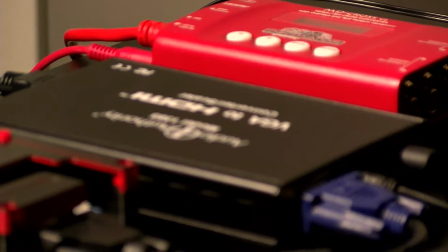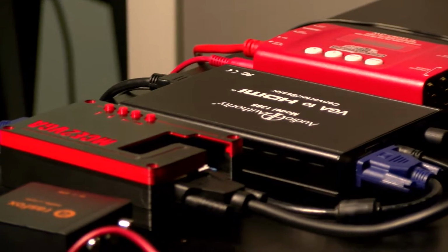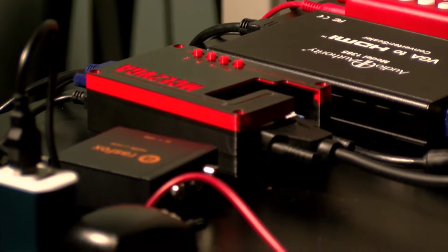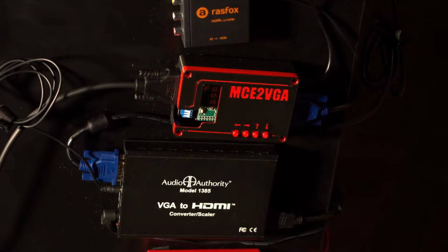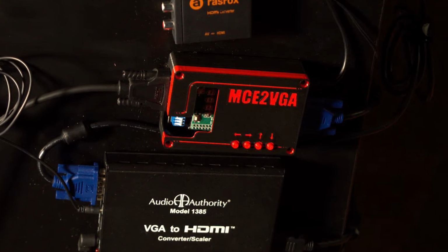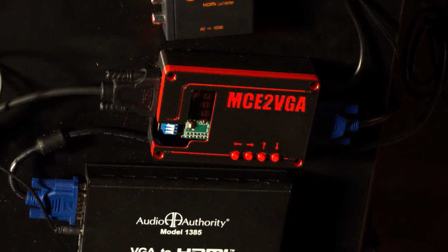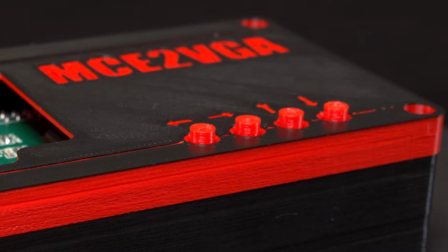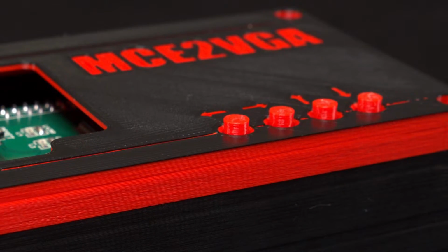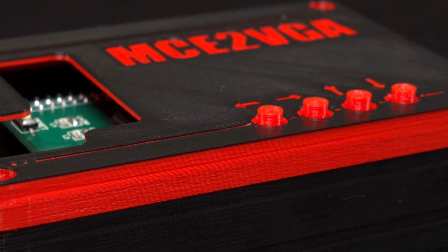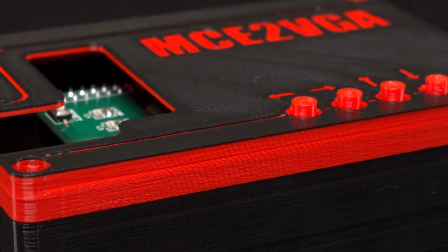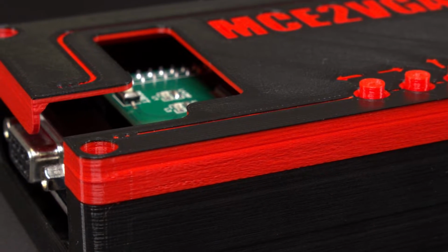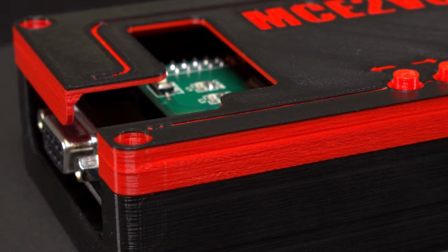Enter the MCE to VGA adapter, which is actually a kit that can be configured to perform a multitude of functions. In our case, we're using it to input the analog parts of the CGA signal and format the output based on the digital information encoded in the input signal. Scaling is not necessary at this stage because VGA, by design, supports all of the resolution and color depth of CGA. Aspect ratio, refresh rate, and screen size are also identical at this step.